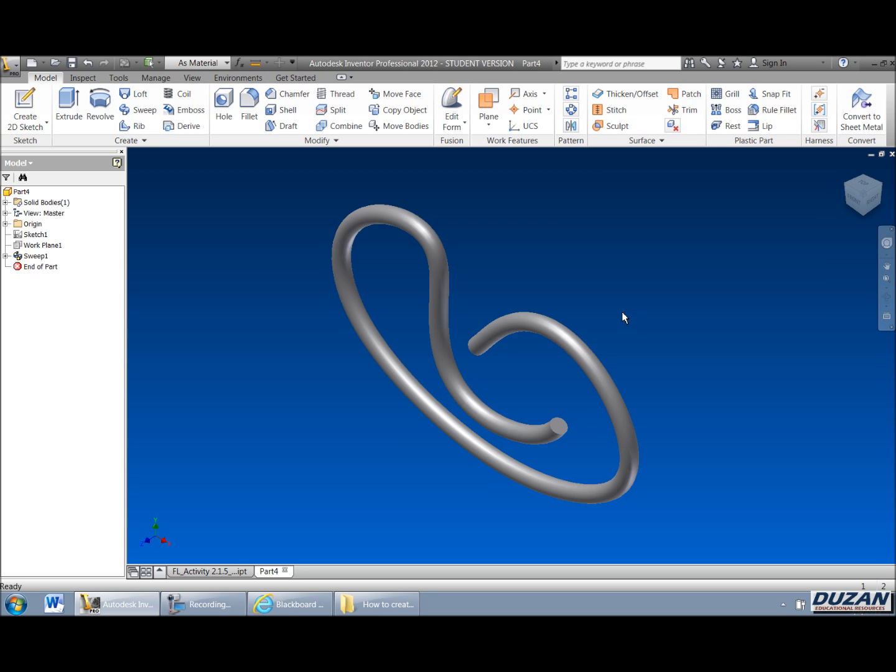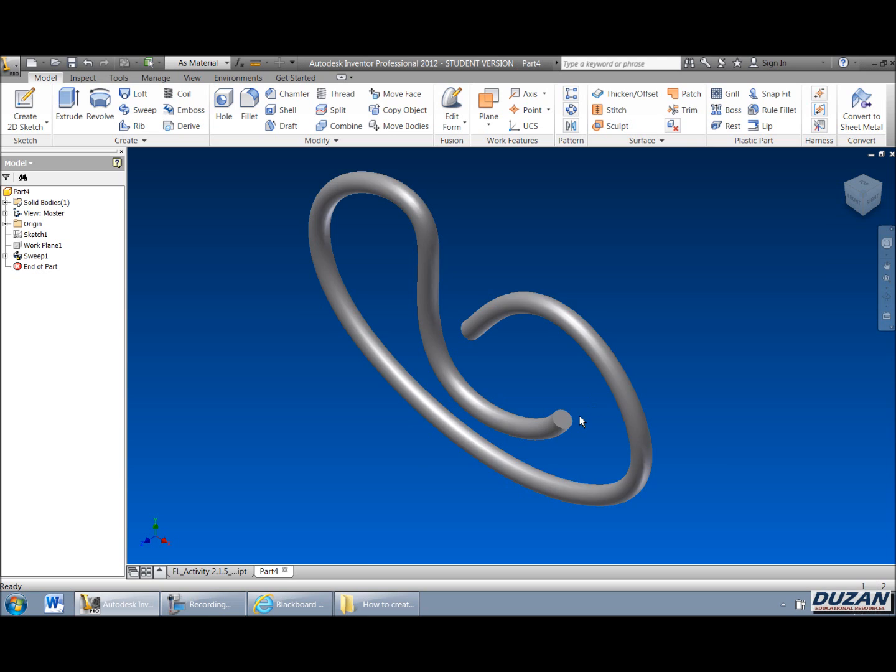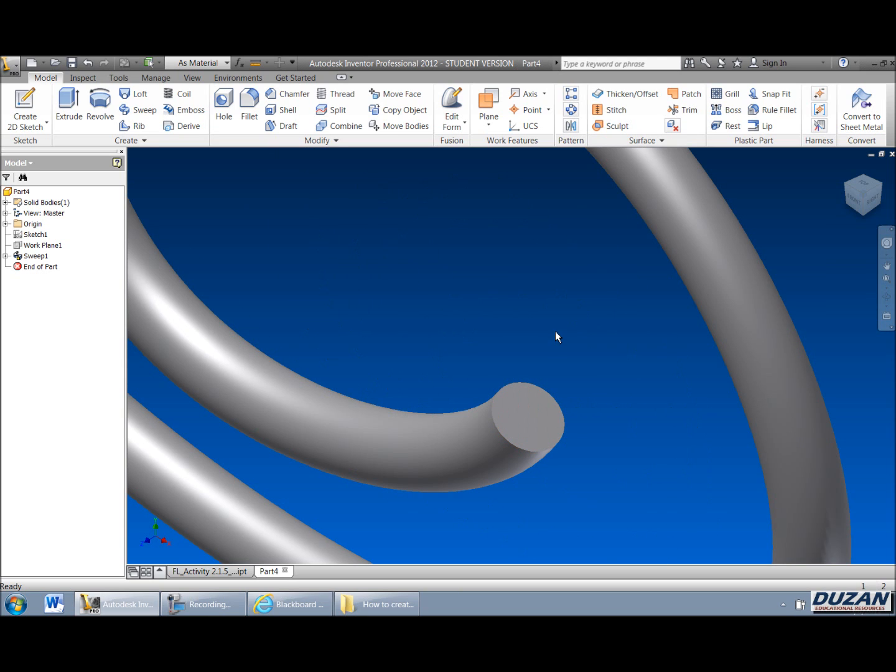All I did was simply use a spline as a sketch, place a work plane at the end of that spline, and create my circle to extrude along that path through the use of sweep. Right now it looks like we have a hose with a diameter of 1, and we want that to actually be a hose, so we have to hollow all this out and apply a thickness. In this case, that thickness is 1/16 of an inch, so 0.0625.